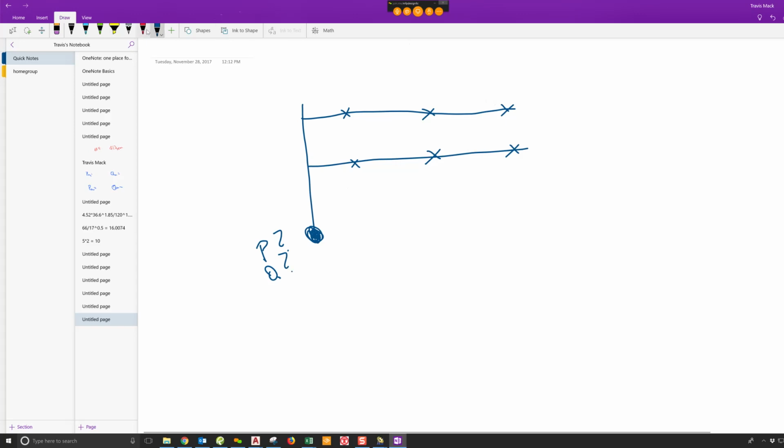At this point, we're going to say that each sprinkler is, let's do it, 18 GPM. And let's do a 5.6K, okay? This will be 1 inch, 1 inch. Yeah, let's just make it really crazy. 1/4. Okay, 10 feet. I'm just doing the 10s and the 5s for easy math. This will be 3 inch schedule 40. And the only reason why I picked 3 inch is because I know the internal diameter of 3 inch schedule 40.